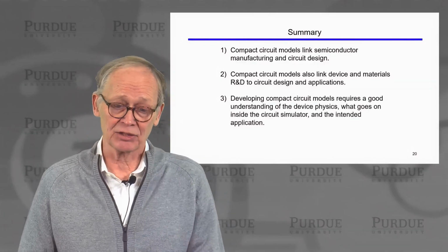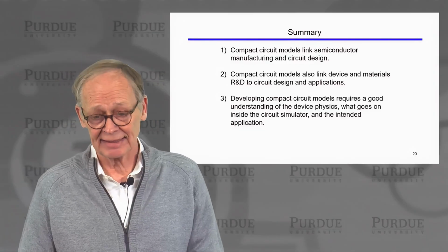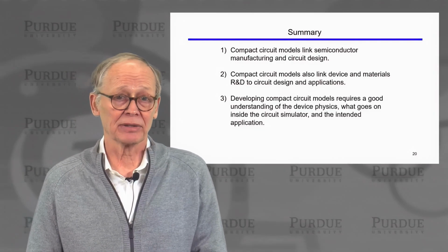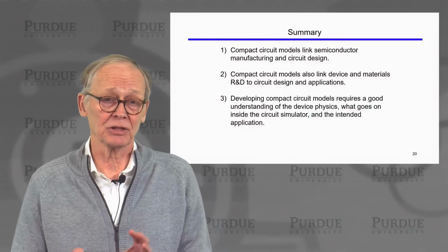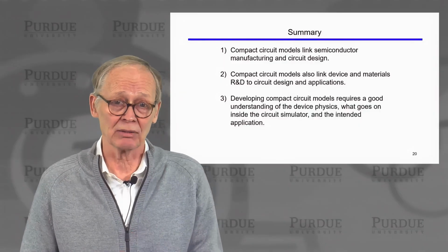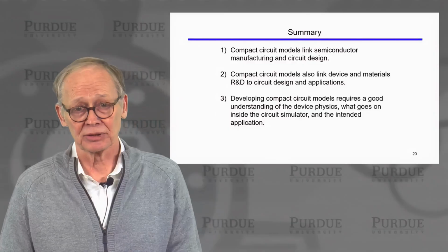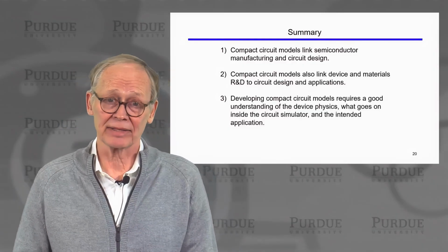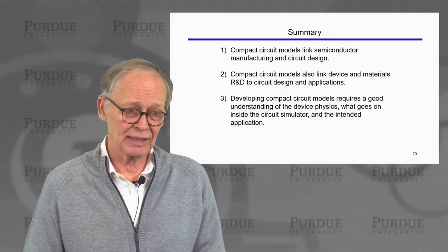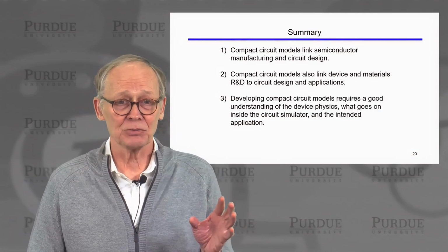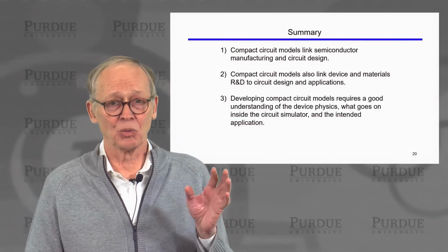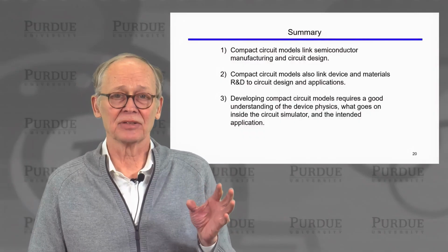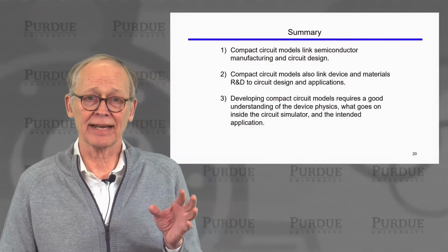Developing a new model requires a good understanding of the underlying physics, but it also requires an understanding of how the circuit simulator solves the circuit equations so that you can make sure that the model behaves well in the numerical solution of the circuit equations. It also requires an understanding of the intended application. It's not useful to spend too much time making your model 1% accurate on an aspect of the performance that doesn't have a significant impact on the application.